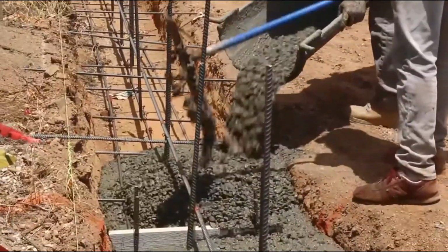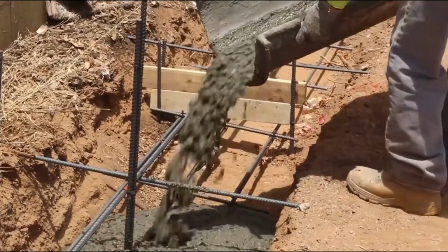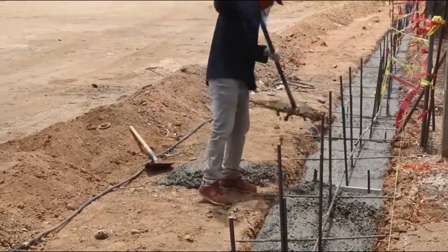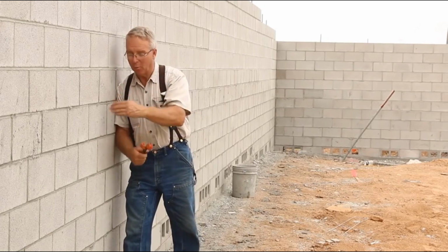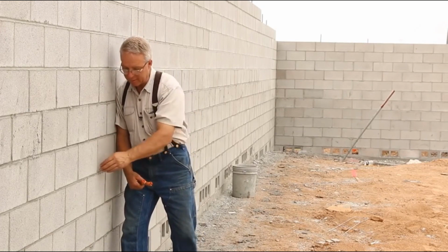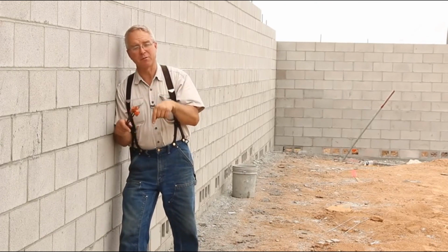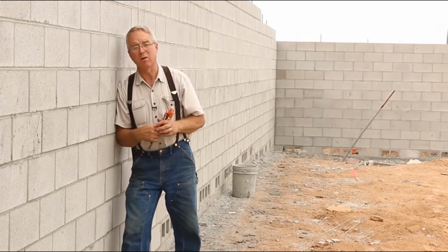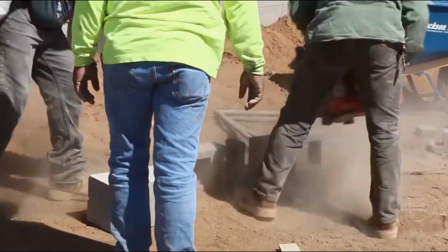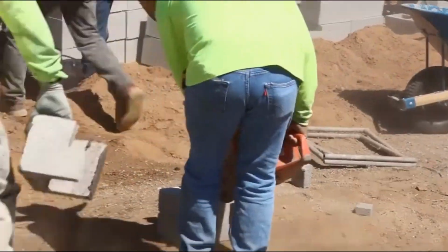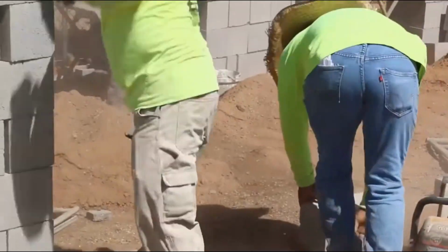And one of the things that I have learned over the years, that these guys are illustrating, kind of went against the grain for me, and I wasted a lot of time. I used to try to set the bulkheads for the steps at the point that the bond would happen on the brick. That's a waste of time. When you're setting bulkheads for steps in the footings for a block wall, just throw the bulkhead in, and then the mason will cut the block to fit the condition of the step. You don't have to build the step to match the bond on the block.